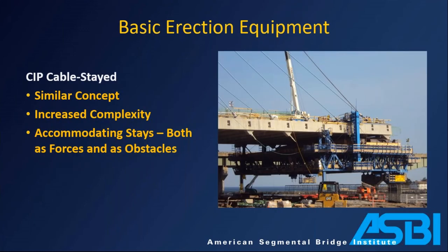They do get a little more complicated as you start looking at other types of construction. When you have things like stays to worry about and kind of funny shapes to avoid, you need a lot of raising and lowering to advance them. So they can get to be very complex. They can get to be very heavy, and it can be a pretty important part of the design, right? It's on the order of 50 to 60% of the weight of a segment. So it is significant when you're looking at the construction engineering.